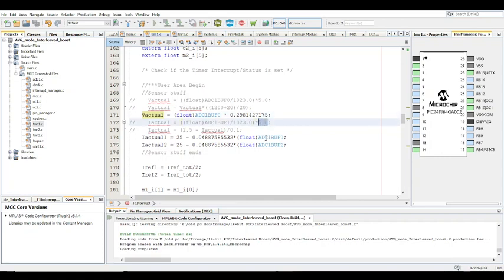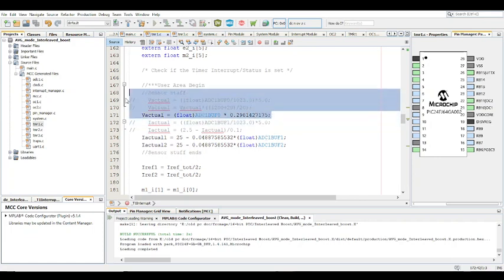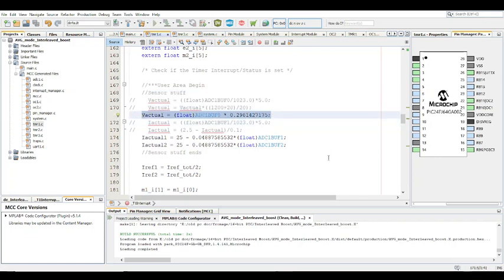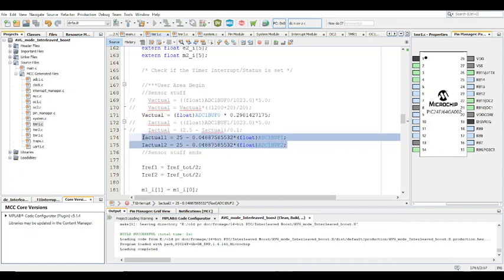here. That's important. Remember, if you're not sensing the proper values, you're not calculating the proper values, you're basically not going to control anything, right? Well, you might control something, but it's just going to be off, and you might destroy your components in the process. So it's important that this is in order, and that you redo the calculations, because this is for a 10-bit ADC and 5 volts VREF, and the current sensor in this case is 100 millivolts per amp.